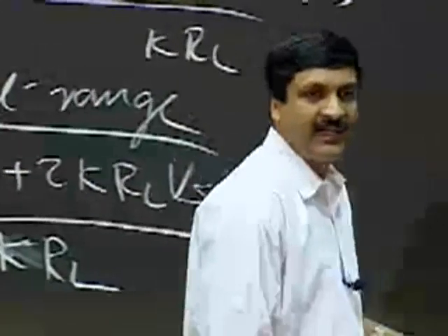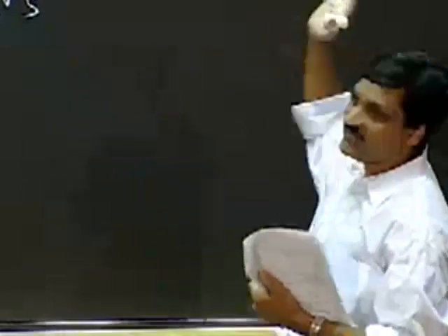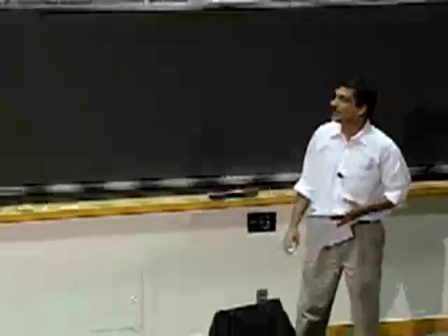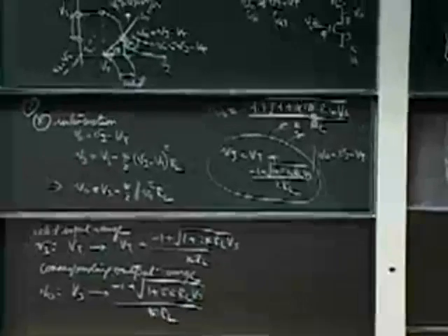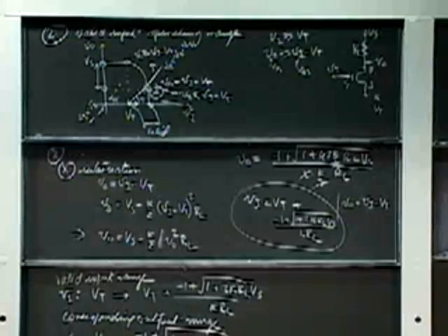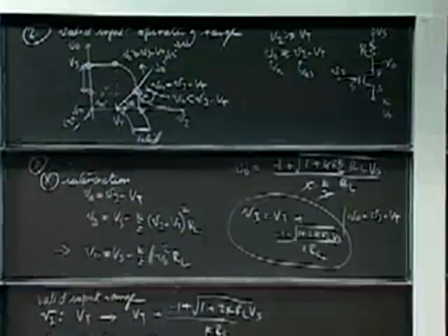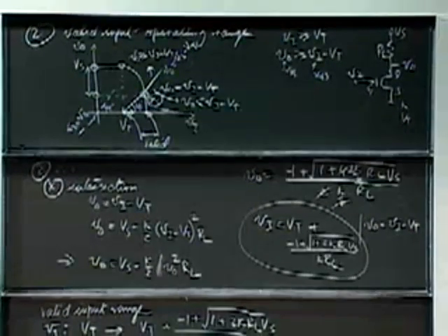It's pretty amazing as you get into this business and keep going down the path. It's amazing how some people really intuit or really kind of get the load line thing, and others feel much more comfortable with the transfer function. So, pick whatever you want. Okay. So what we have so far is we have conducted a large signal analysis of a MOSFET amplifier. Okay, it's an analysis of a circuit, and we found two things. One is the transfer function under saturation operation, and we found the valid input operating ranges and the corresponding valid output operating ranges for the circuit.